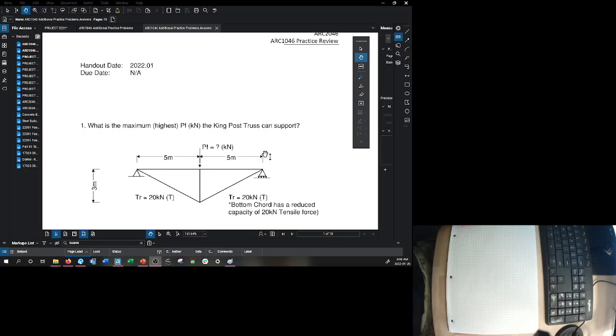So we have a truss, but we do know that when we were bending things, when we looked at my foam block, if there was a load going downwards, the top chord was often in compression and the bottom chord was often in tension, which made it kind of handy to check ourselves when we solved some of these things.